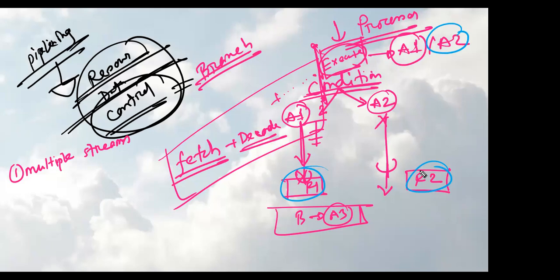That means all the underlying instructions are already executed, and I have multiple results in my hand, but which result I will follow will be decided in this execute stage. But there are some limitations, because if there is multiple nested branching, at that time this approach will fail.